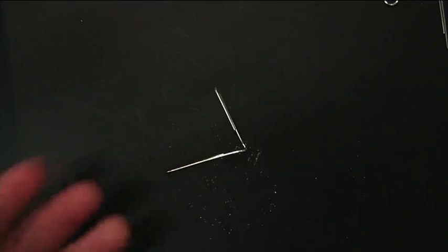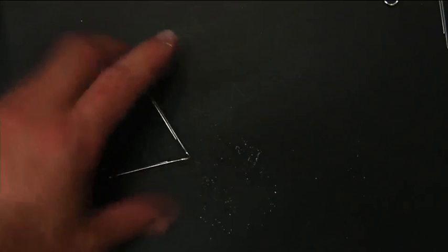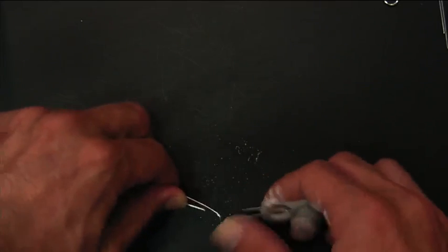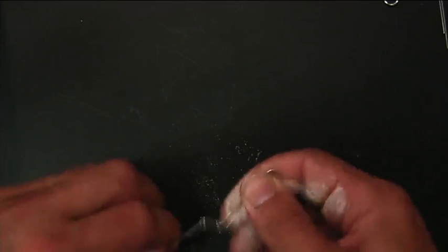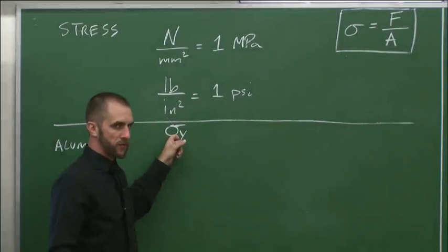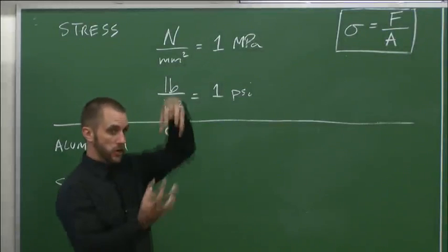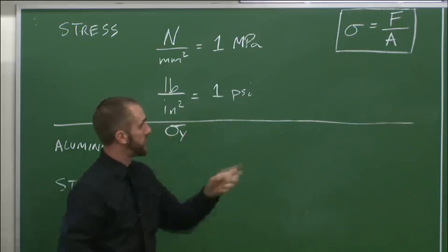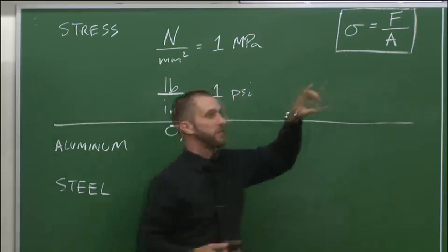Hopefully you can see. You can do this at home. You can bend it, it's kind of springy, and then you just keep bending it. I'm yielding, you keep going. It's actually a pretty robust paper clip, but eventually you'll break it. So that's where there's a stress level. I wasn't doing uniaxial stressing. I was bending it. That's a different flavor of stress.